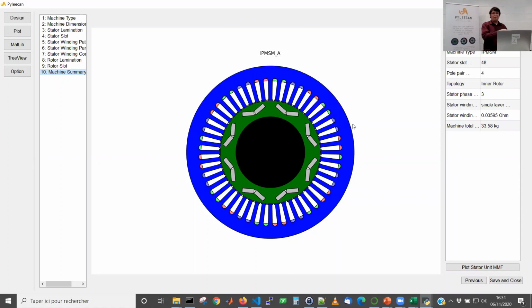For instance, if I want, now I can go into the script, take the list, these three surfaces, do a translation to put it on 0, do a rotation, another translation, and provide the new list of surfaces to Pyleecan, and boom, I will have returned the previous magnet. It's that simple. Again, as long as it's in the black box that returns my list of surfaces, whatever is inside the box, it works.